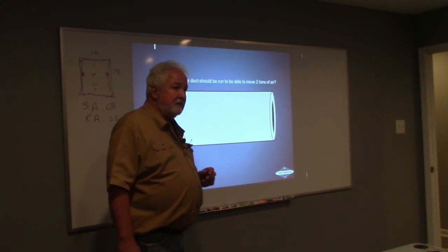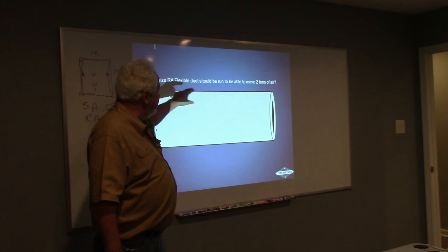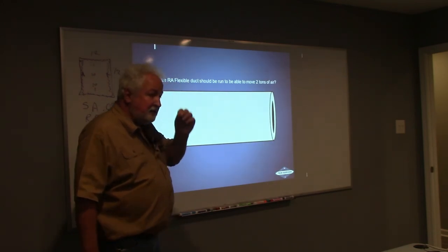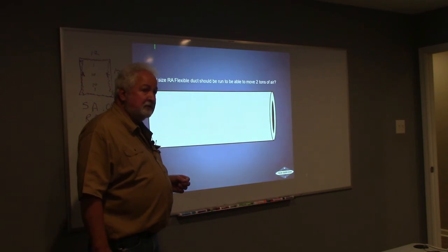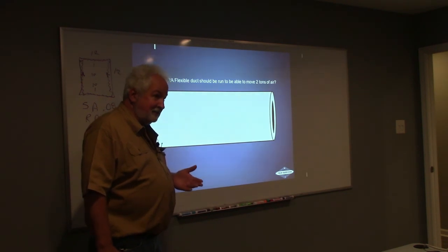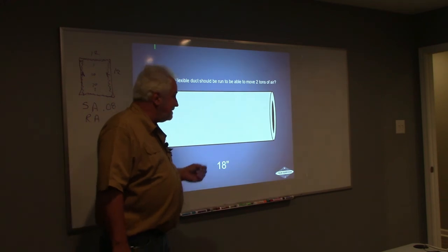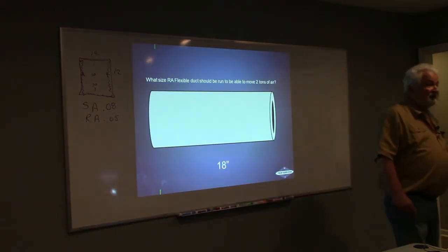Then look at your round and see what it comes to. You got 800 CFM through that 0.05, so line up 800 to 0.05. So what size duct? It's between 14 and 16. Yeah, 800. I'm gonna go with a 16, because I can't damper up, I can only damper down. Good. I'm gonna tell you it's 18. Look at it and see, I think you'll see that it's 18. I think it falls out at about 17 if I'm not mistaken.